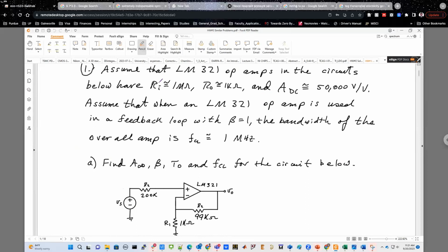The only thing that will be asked in terms of closed loop bandwidth is whether you know that closed loop bandwidth is 1 plus T naught times the open loop bandwidth. Or you can say it's just T naught times the open loop bandwidth, it will be very close, and that's fine. If your gain reduces by T naught times, your bandwidth has to increase by T naught times. That's the crucial part.